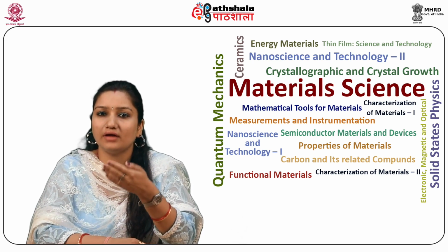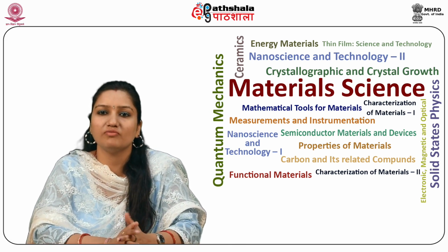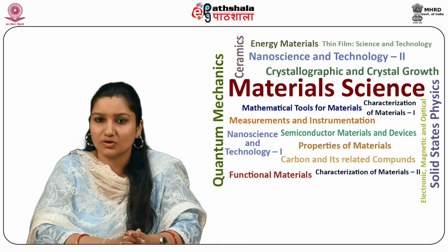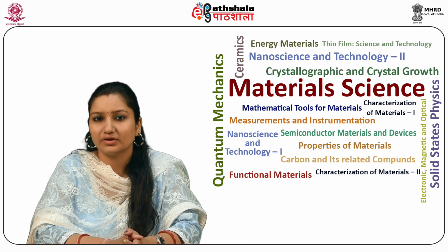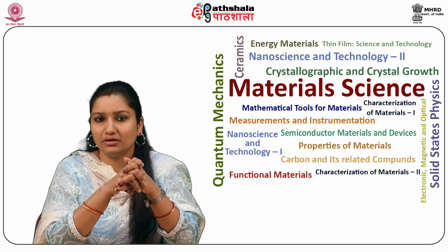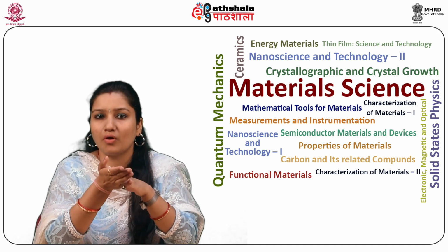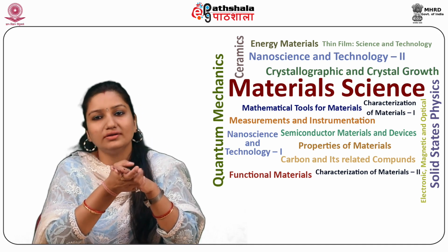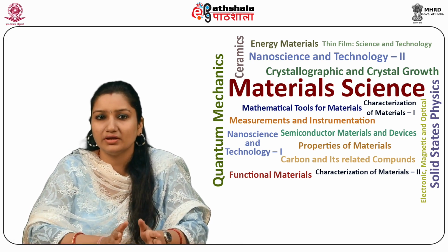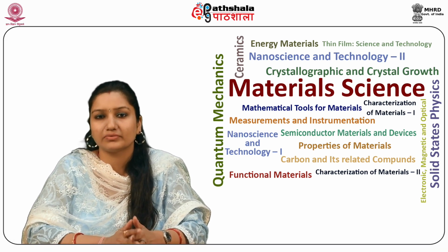Atoms from a solid target source are ejected or sputtered via a process of momentum exchange inside the plasma by the action of high energy ions, usually originating from some inert gas ambient like argon. The ejected particles are then deposited or condensed on the surface of the substrate to produce a thin film. So sputtering is a vacuum coating technique.